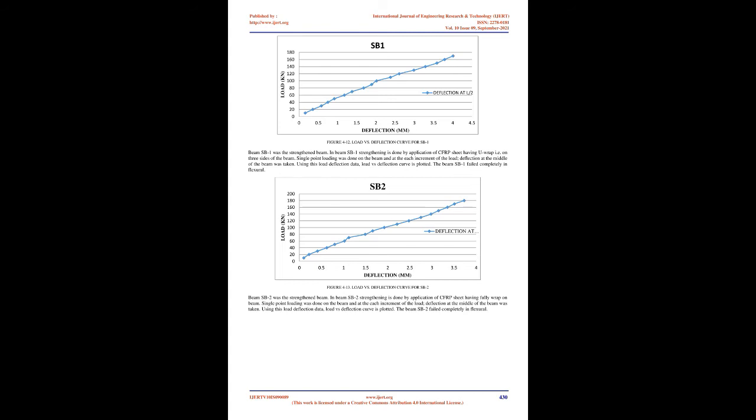Experimental data on load, deflection, and failure modes of each of the beams are obtained. The change in load carrying capacity and failure mode of the beams are investigated as the configuration of FRP is altered. Beam 1. Control beam, CB. The control beam, CB, is not strengthened with CFRP sheet. It is checked for its ultimate load bearing capacity under single point loading setup.